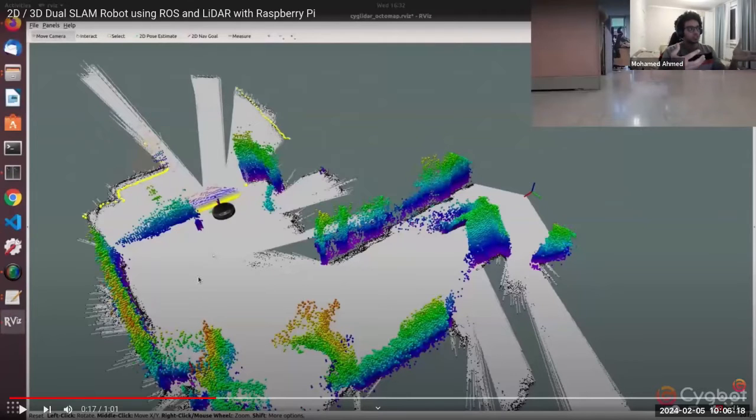What we are doing here is taking the data from the camera and the data from the lidar, and running algorithms to know the position of our robot in the real world. Then we are trying to see which are the free cells, or the drivable areas where we can move, and where the obstacles are. As you can see, it is only allowed to move on the white cells.